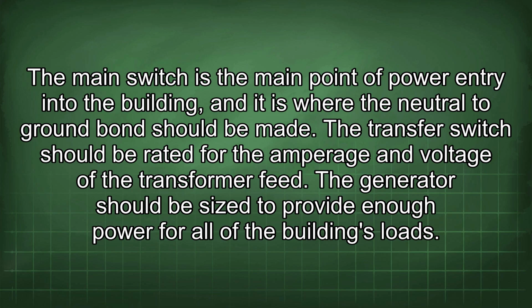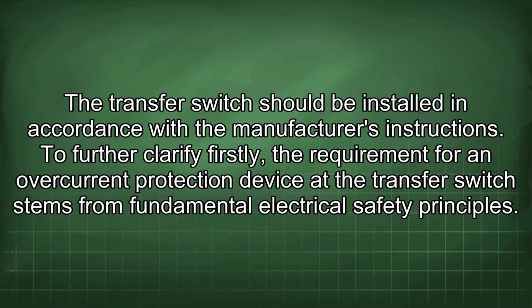The transfer switch should be rated for the amperage and voltage of the transformer feed. The generator should be sized to provide enough power for all of the building's loads. The transfer switch should be installed in accordance with the manufacturer's instructions.